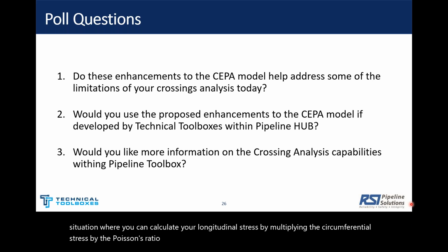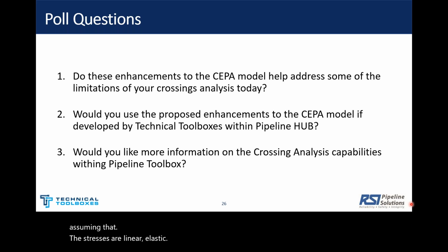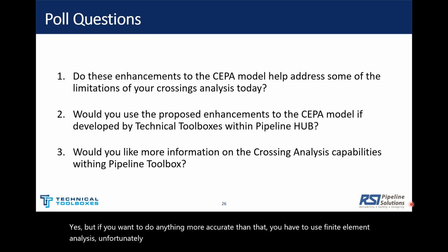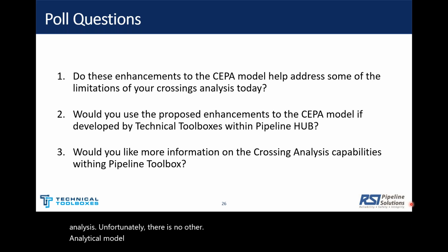Now, we use a couple of assumptions here. For example, we are assuming that the stresses are linear elastic, but that's a reasonable assumption until the pipeline starts to yield. But if you want to do anything more accurate than that, you have to use finite element analysis. Unfortunately, there is no other analytical model that can give you better results.